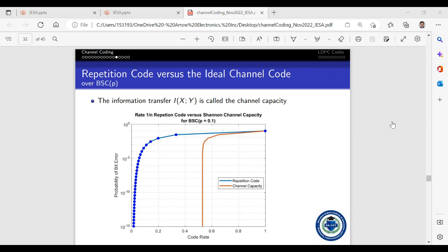And so there, one kind of a middle way out that is being explored today in the literature, even in the industry, is called hybrid beamforming. And I have published one or two papers on that. Although you use maybe 1,000 antennas, you actually use only maybe 20 or 50 RF chains, and then you intelligently switch these antennas across this limited number of RF chains. It's sort of a practical realization of this mathematical end result.